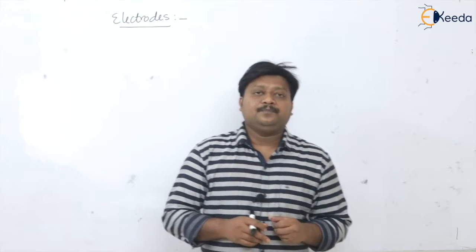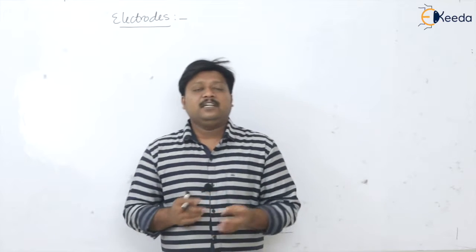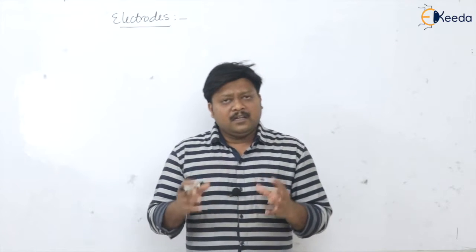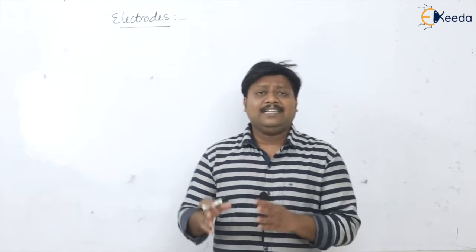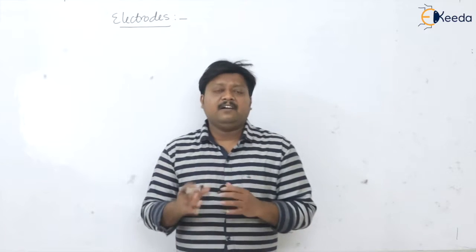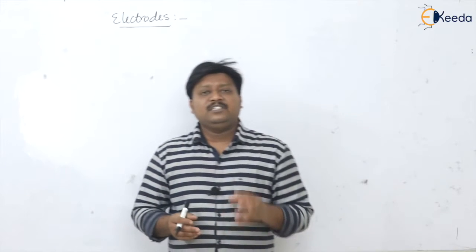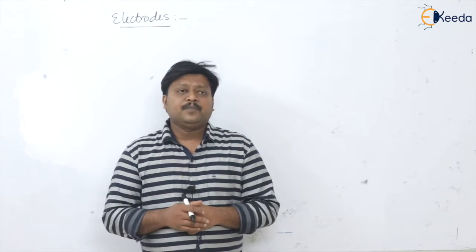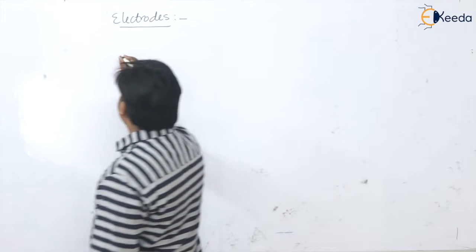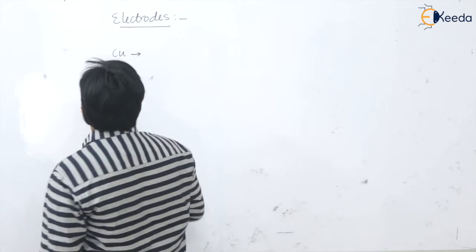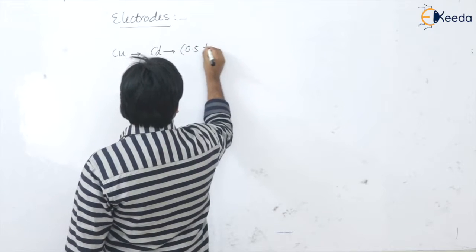So that is why the most commonly used electrode material in resistance welding is copper, having very good conductivity, but it does not have the strength required to withstand these mechanical pressures. So we are using an alloy of copper. In the alloying, we add cadmium into the copper, say from 0.5 to 1%.